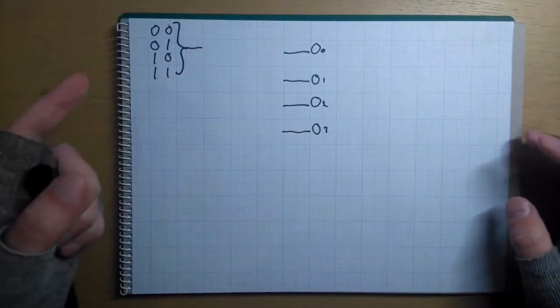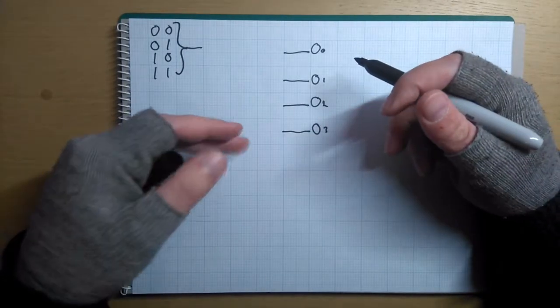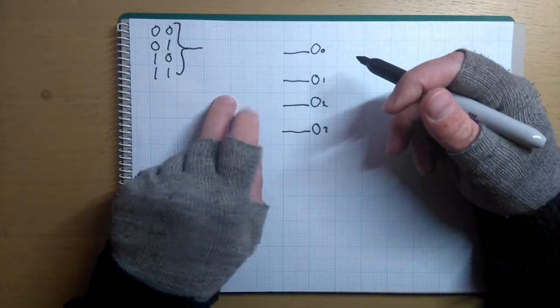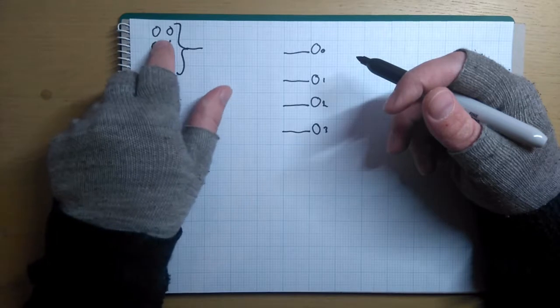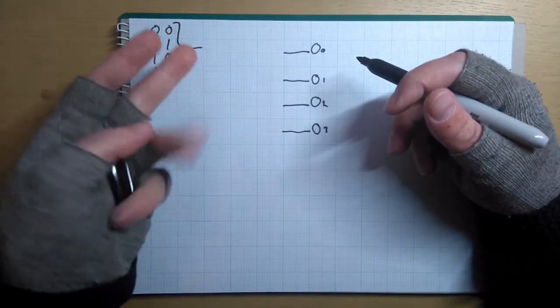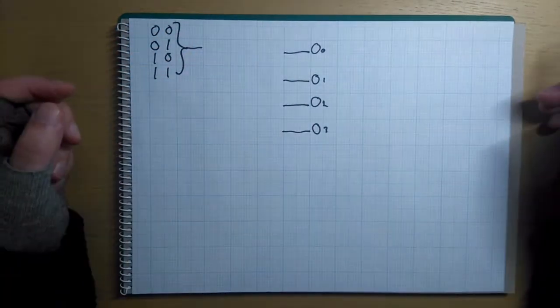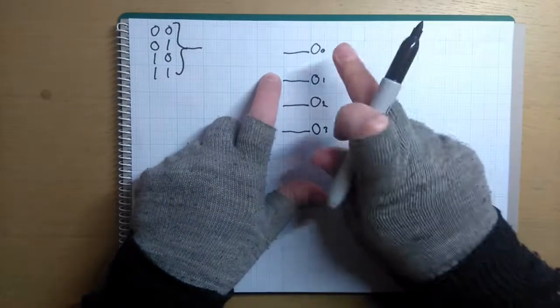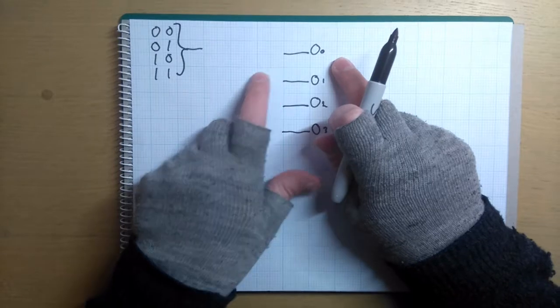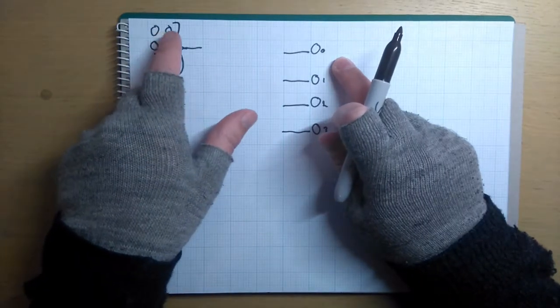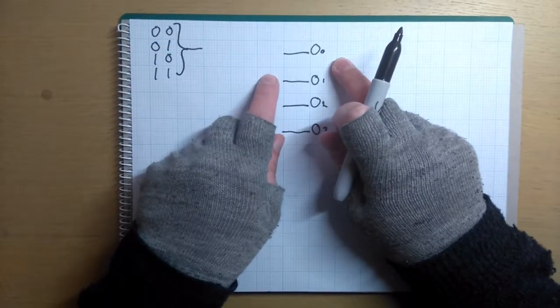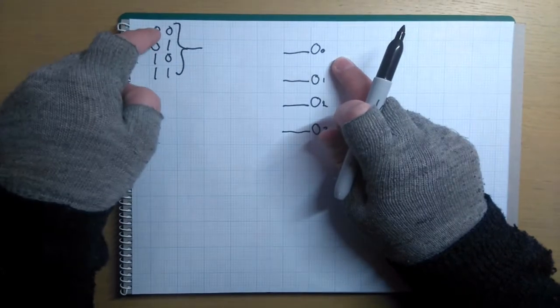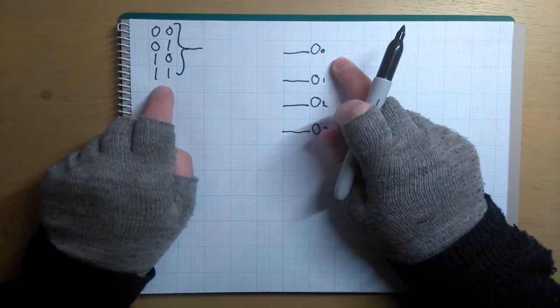So when we were doing 1 to 2, we could just do this with buffers. But this is a little more complicated, as we can't just use a buffer on both bits, because then you still need to compare them in some way. So we have to use AND gates this time. But how would you still represent 0 here? Because 0 and 0 is still 0. So we actually want to invert all these as well.